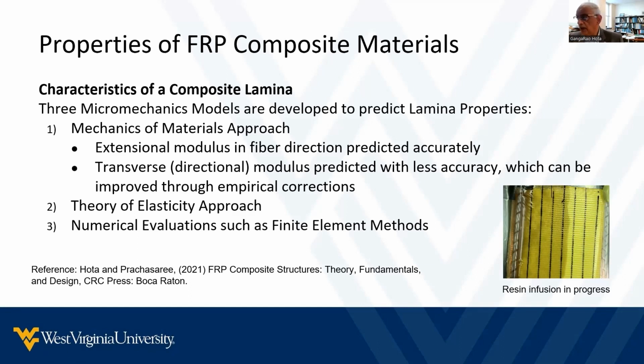And these two properties, longitudinal versus transverse, are going to be somewhat different depending upon how the fabric is laid out, and it could be vastly different, or it could be nearly identical depending upon the fiber volume fraction in the longitudinal direction versus the transverse direction. I will be showing you some of the equation developments in a minute.